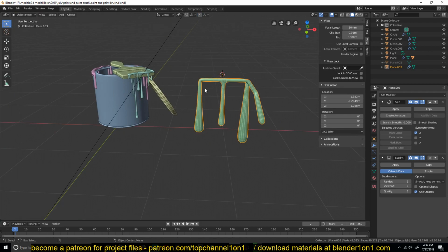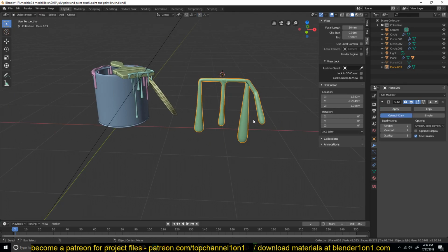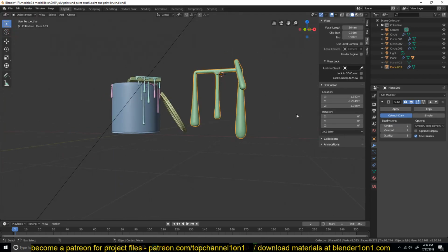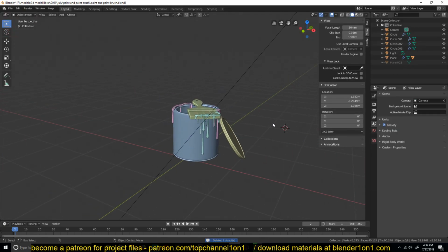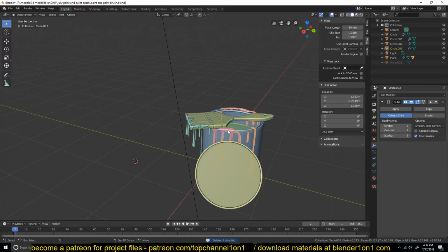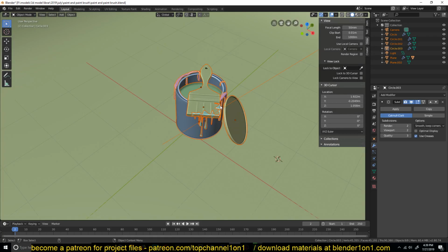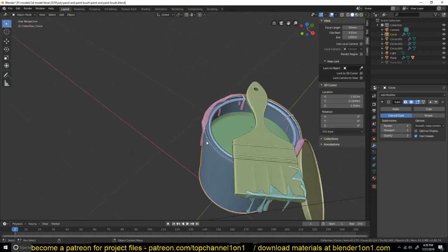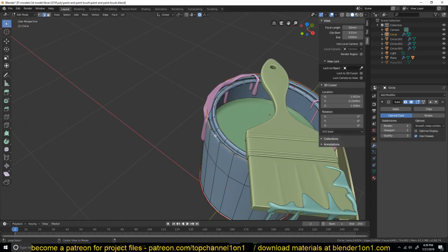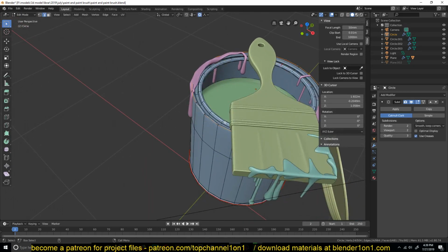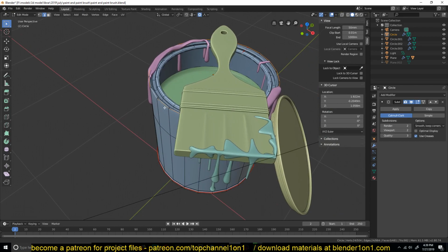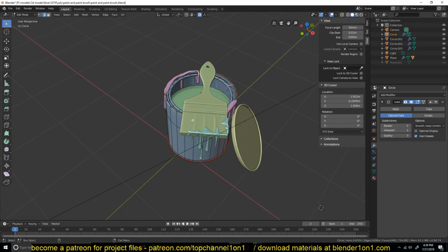And after you get the shapes you want, you can apply the skin modifier and then turn on smooth shading to get that. So you can see for this here, it goes around the paint bucket, and the way I achieved that is that after modeling the paint bucket, I just selected an edge loop like here. You'll see these tricks that I used in other time lapse if you want to watch that.